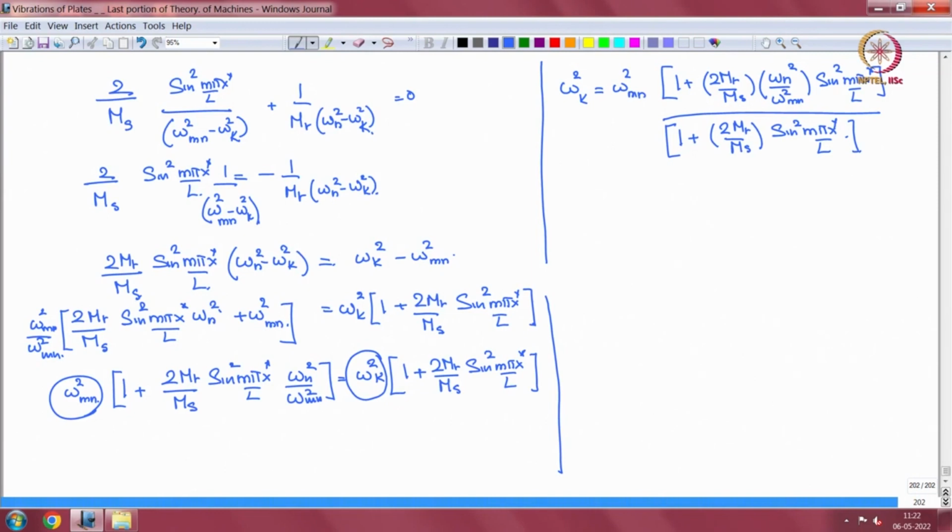So this is under the assumption that the ring that is stiffening the shell is not influencing the resonances very strongly, so that a single term in alpha 11 dominates.